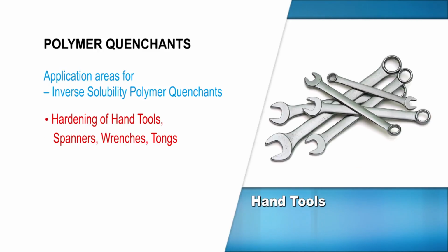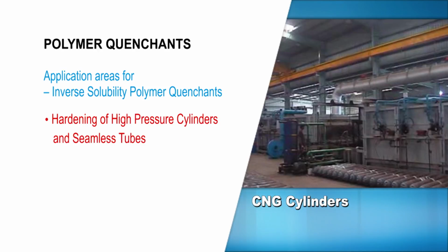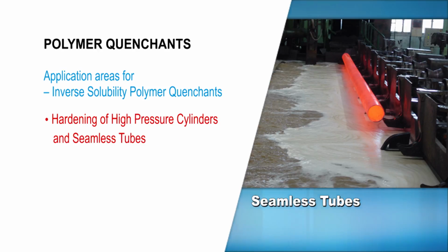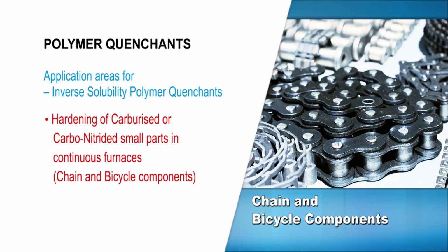Hardening of hand tools, spanners, wrenches, tongs. Hardening of high-pressure cylinders and seamless tubes. Hardening of carburized or carbonitrided small parts in continuous furnaces, chain and bicycle components.